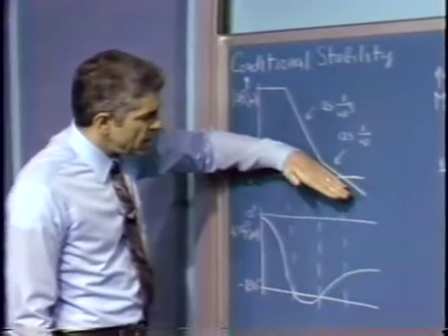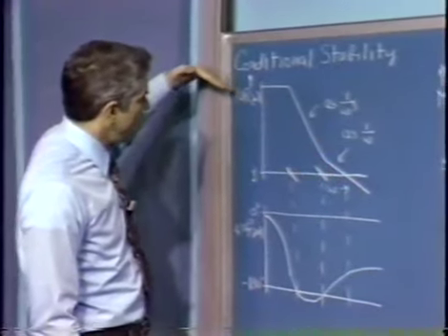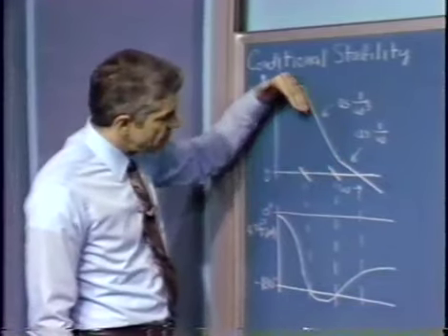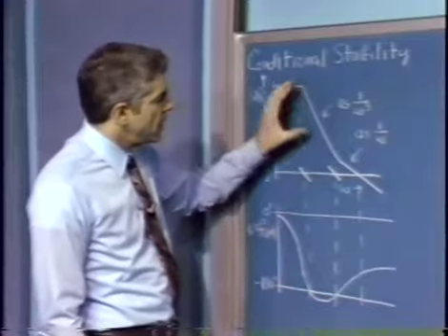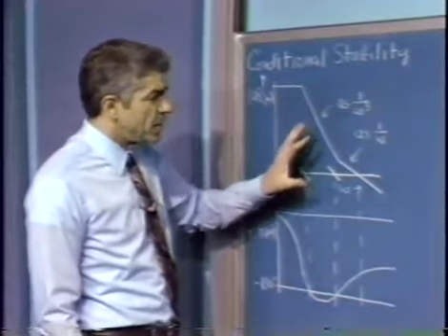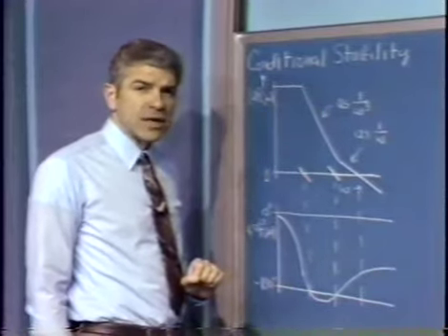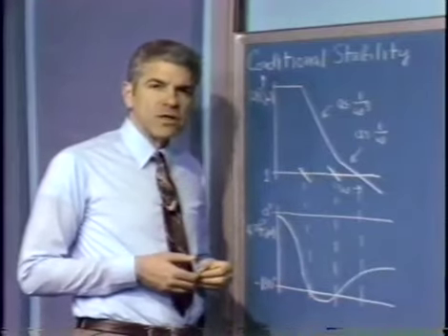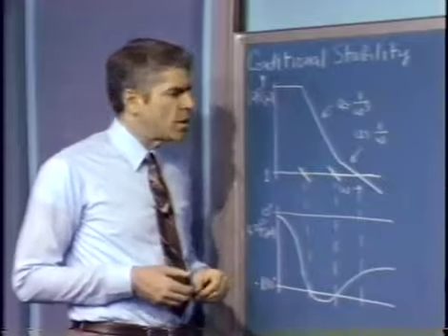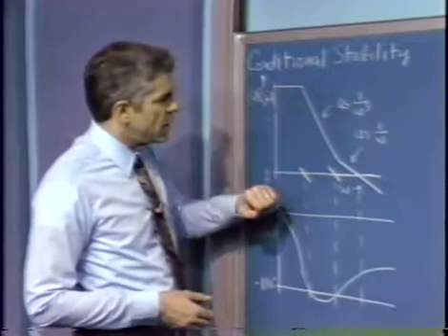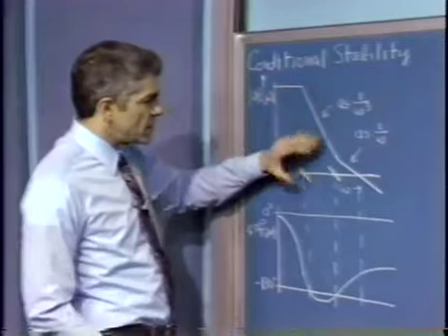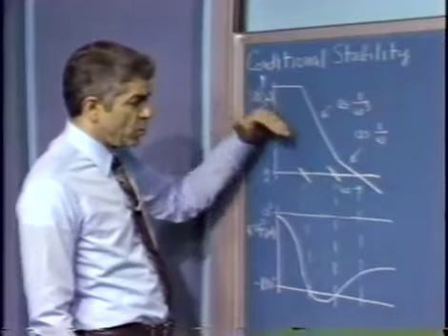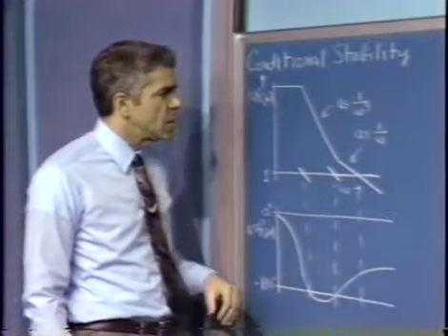But rather than maintaining that 1 over s roll-off all the way back to very low frequencies, we may very easily find it advantageous to have a faster roll-off, 1 over s squared possibly. We looked at that with two-pole compensation in an op-amp, or the kind of transfer function that results when we include a lag network. We'd have a 1 over s squared kind of a roll-off. The reason for that is that we get greater desensitivity over a wide range of frequencies compared to a true 1 over s roll-off at all frequencies.